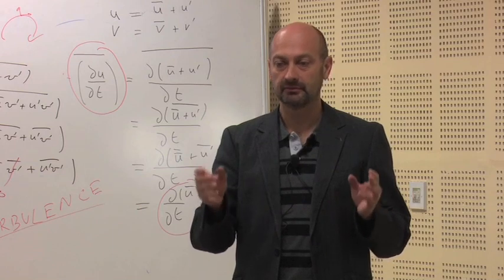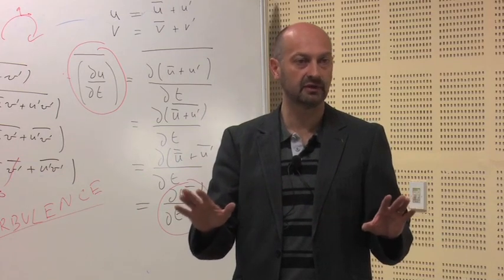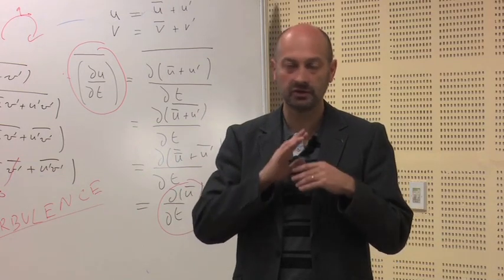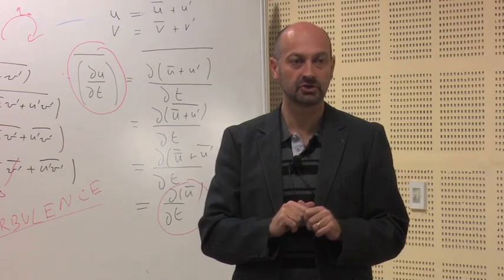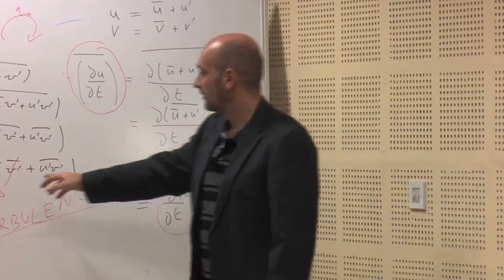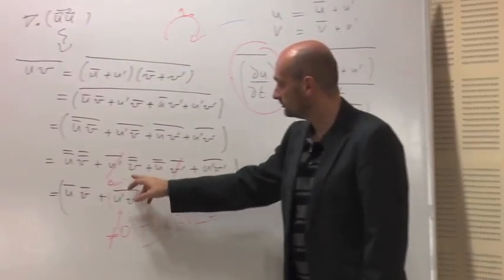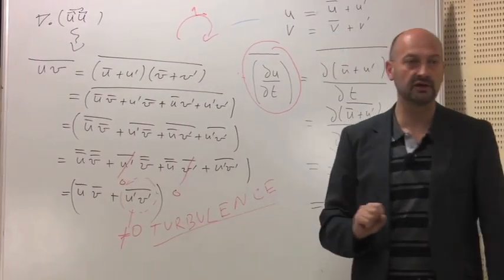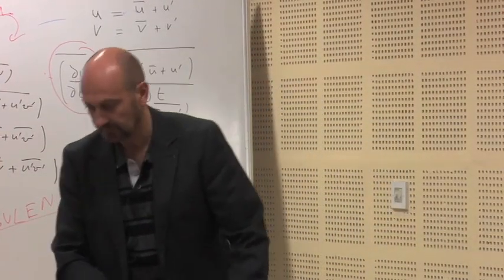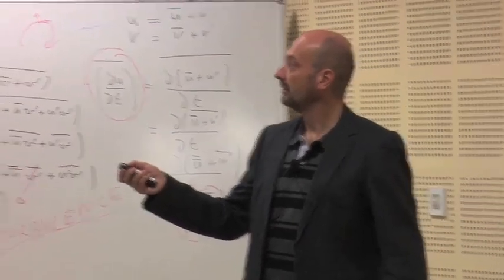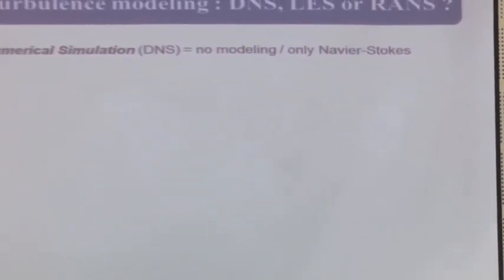But if you do simulation but you don't have any background in fluid mechanics, you are going to do wrong simulations, just because there are modeling issues. There are modeling issues in CFD. If you do direct numerical simulation, there are much fewer problems, because you solve exactly the Navier-Stokes equations without any modeling. So you cannot make too many mistakes.